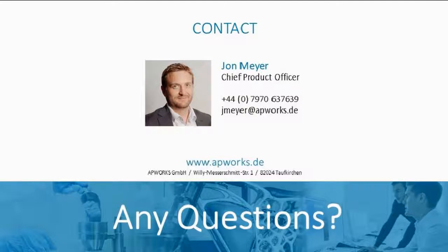Okay, good. We still have a couple of questions on the material side. The next question would be whether there are any high temperature alloys available for additive manufacturing. So I guess that depends on the definition of high temperature, but yes, there's some quite interesting ones. Inconel 718 and Inconel 625 are quite commonly used in additive manufacturing today.